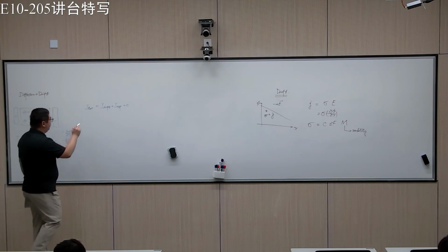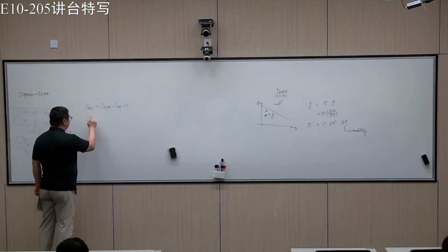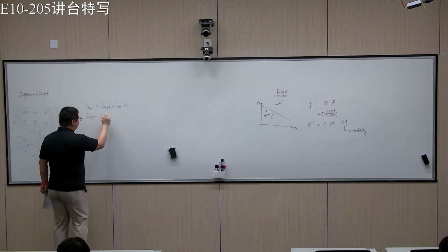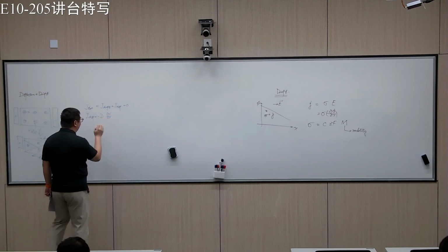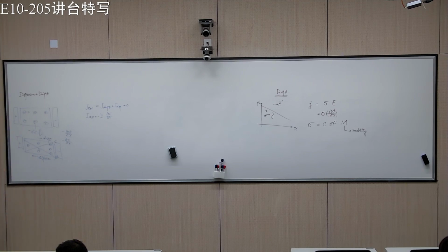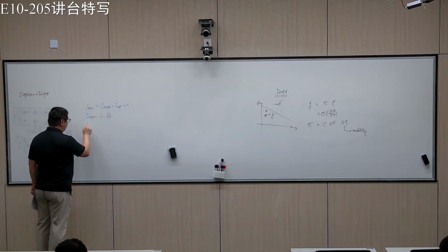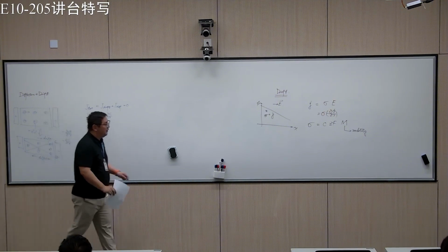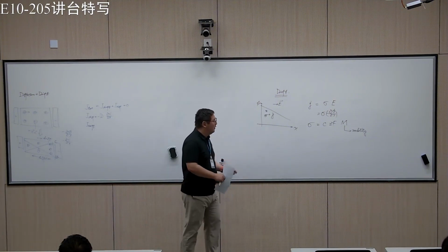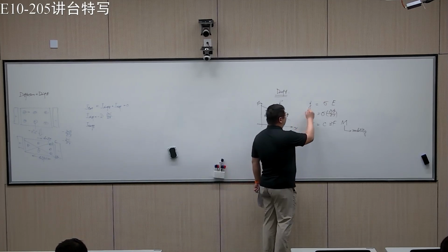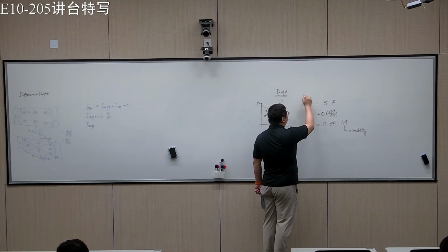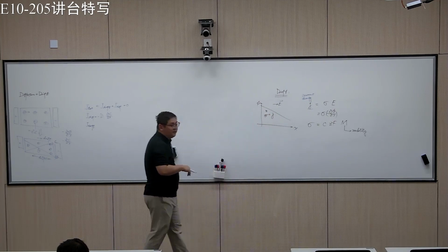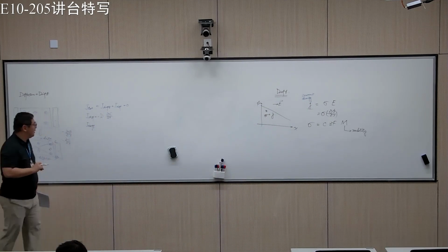We know that the diffusion flux is governed by Fick's first law, sorry, first law. It's basically this one. Then the drift is governed by Ohm's law. However, knowing Ohm's law here, this is the current density, or in other words, the flux of charge rather than the flux of particles, right?